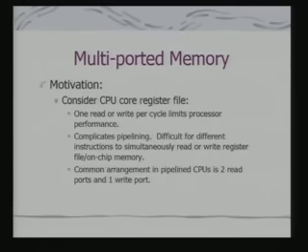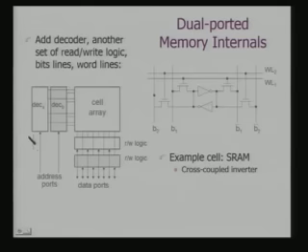So, you can see that we have in some cases dual access memory, and single access memory. In dual access memory, 2 read ports and 1 write port is a common arrangement, so there are simultaneous reads from the memory block. What does that mean effectively? If I am talking about a multi-port or dual port, it means that I have additional decoders.